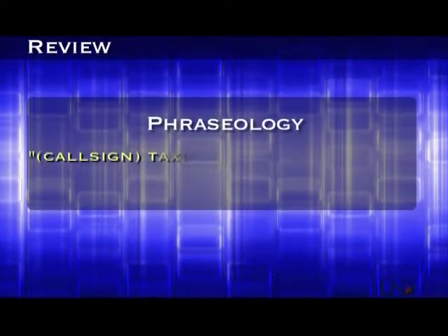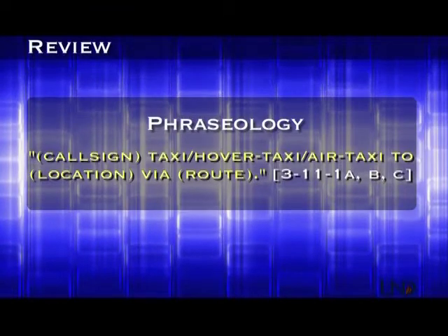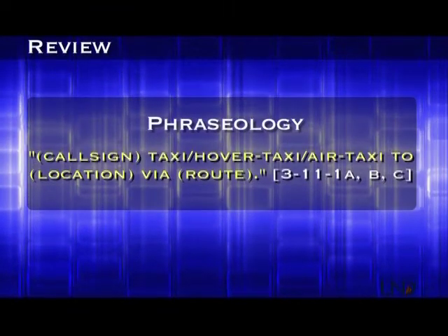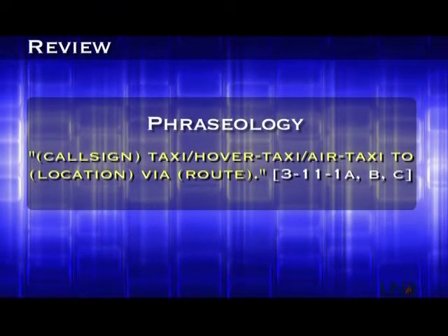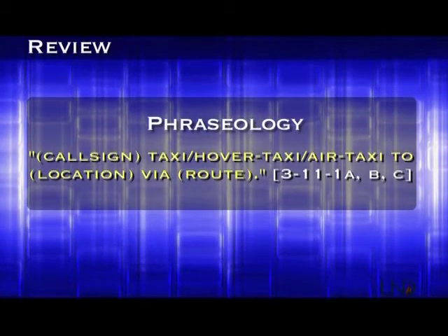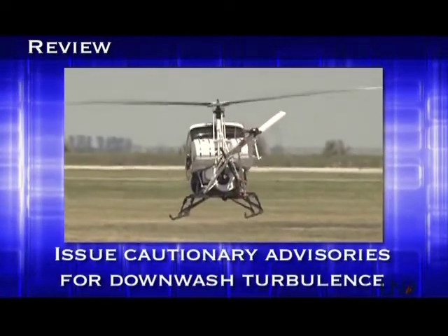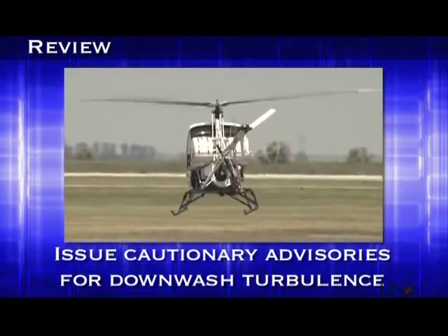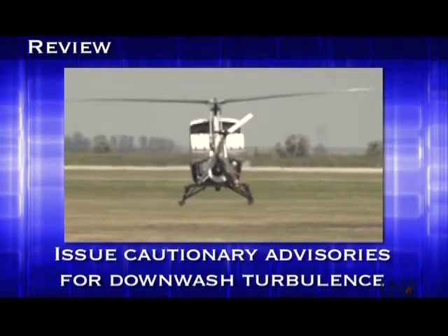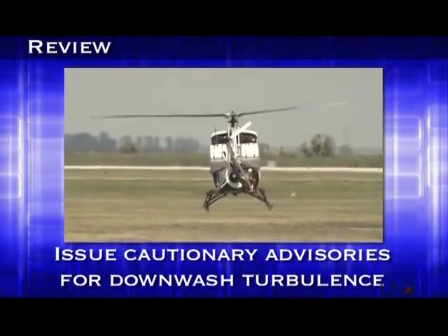The phraseology for each operation is very similar to what you'd use for fixed-wing aircraft. If a wheeled helicopter is ground taxiing, the phraseology is identical. Otherwise, simply say hover taxi or air taxi instead of taxi. Hover and air taxiing can stir up debris such as snow, sand, and rocks, so be aware of aircraft, vehicles, and personnel operating near helicopters and issue cautionary advisories if necessary.